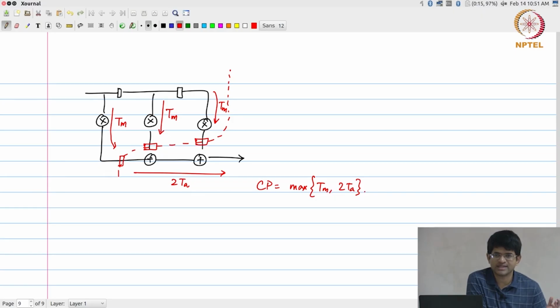And as long as I do that complete division into a before and after segment and I am able to introduce registers on all the edges that go across that, it's a safe transformation. I can safely introduce registers over here without changing functionality, and by introducing registers over there I can hopefully reduce my critical path, and this is a valid pipelining.